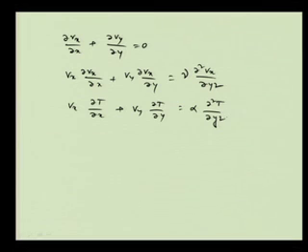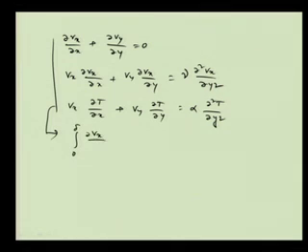What we could do is, when we try to find it in the integral mode, that means if we do the integration of these equations and suitably arrange, we also can come up to the momentum integral equations and energy integral equations. These equations can be converted to this form: integral 0 to delta del Vx by del x plus integral 0 to delta del Vy by del y is equal to 0.